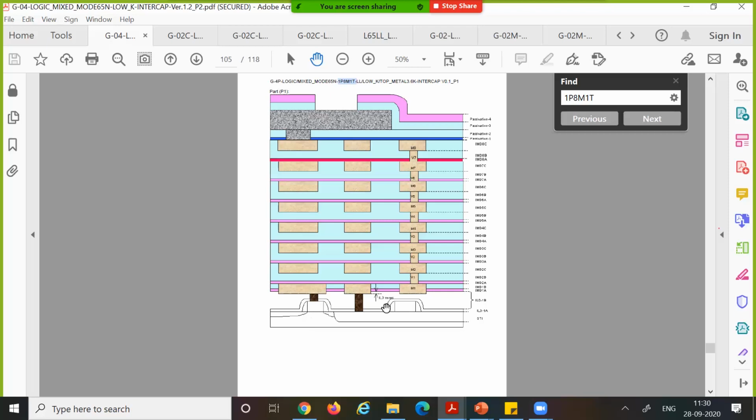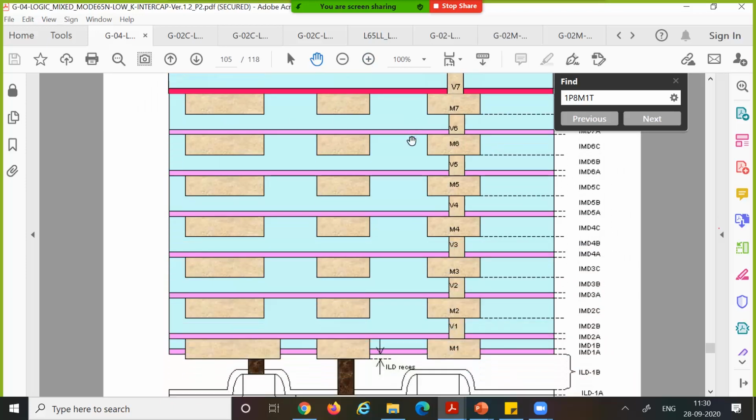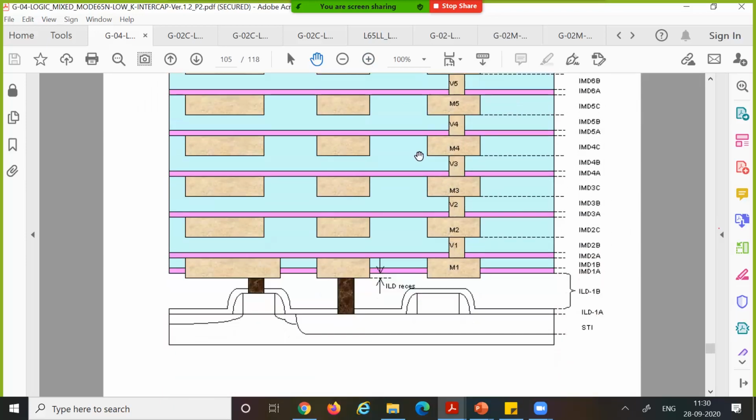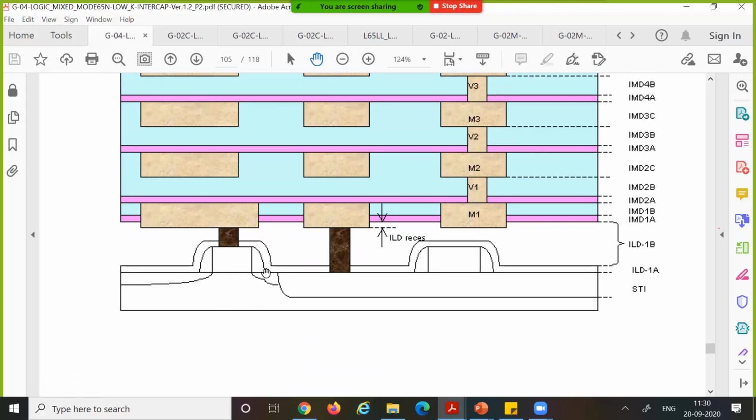And these are your devices, and then you have different metal layers. In this particular option, which I'm showing you, it has 8 metal layers. Now, if you zoom into the bottom, this is basically your basement, or your foundation. This is your substrate. This is an NMOS device. You have diffusion for your source as well as your drain, right?